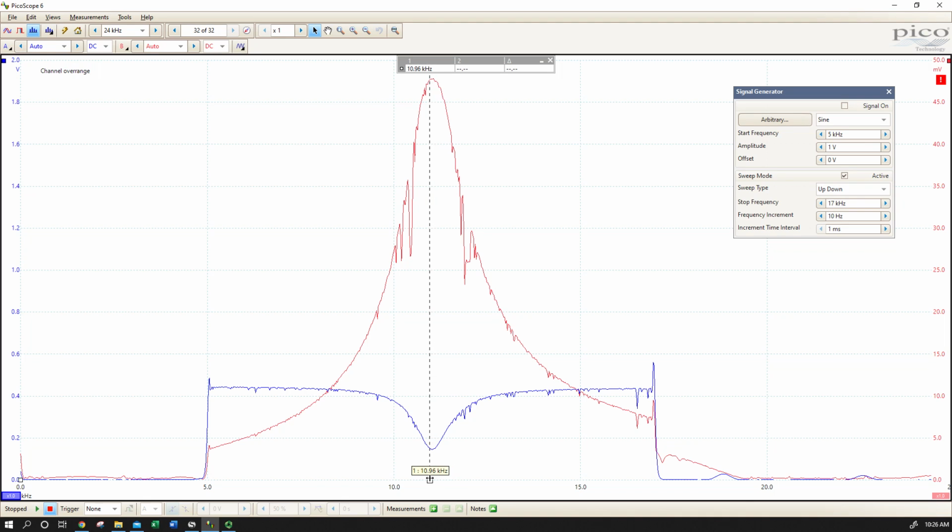So we're using our slider, which is now telling us frequency, and let's look at the low point. And what is that? 11.02, almost exactly what we measured with a scope. But this was a lot easier.